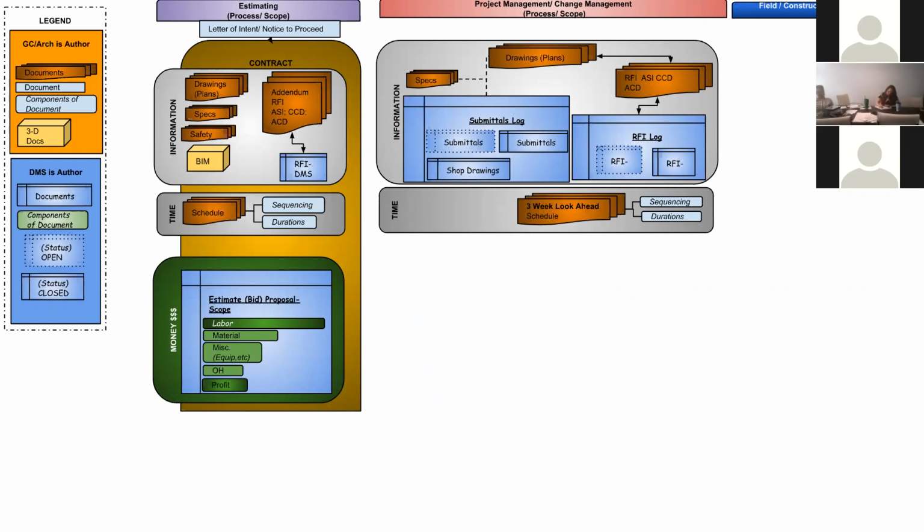The component with regards to drywall, we have to make sure that the building is dried in. I saw an example of that with, I think, Sutter or Central Elementary School, where the building was not completely dried in. They didn't have windows and certain things in, and it rained, and all the standing water is now seeping into the drywall, which creates water damage. When there's water damage, that means you've got to rip down drywall. There needs to be fans, and you have to reinstall drywall. Their concern is mold spores.